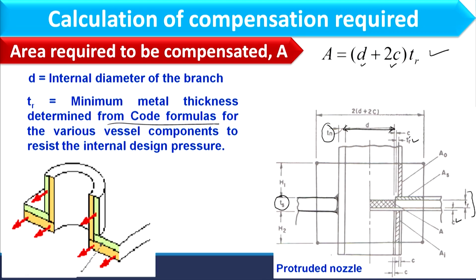Okay. Now, here you can argue that once I have removed the opening in a circular way, why have I considered the area to be compensated as the area of a rectangle. If you consider this image, here we have this particular section which I have considered during compensation. Okay. So, why is it a rectangle? You can understand through this diagram as well as through this diagram that this much area is basically used where hoop stress will work.